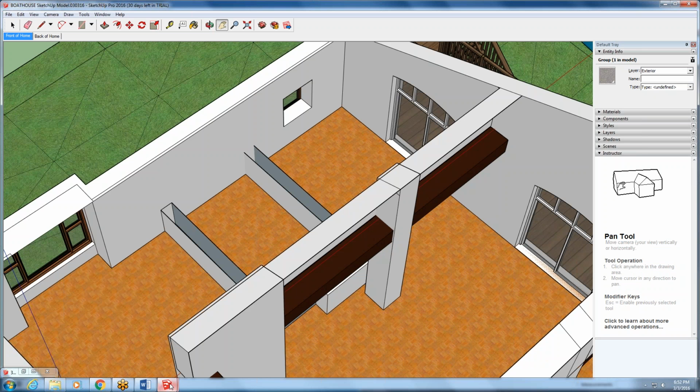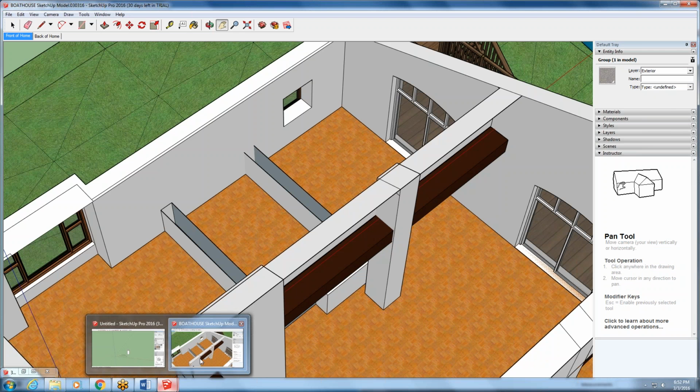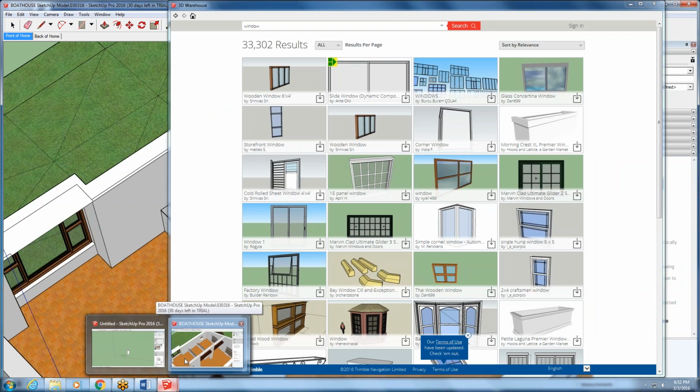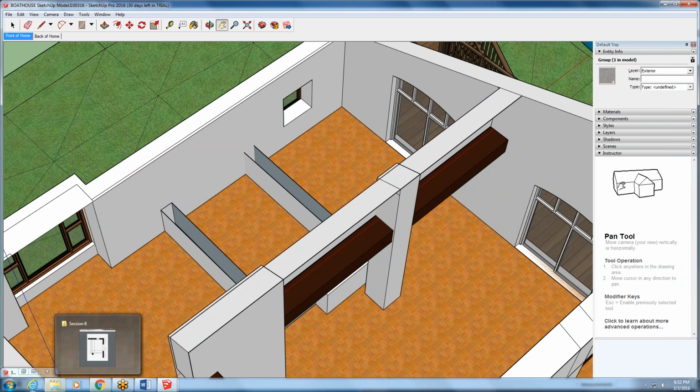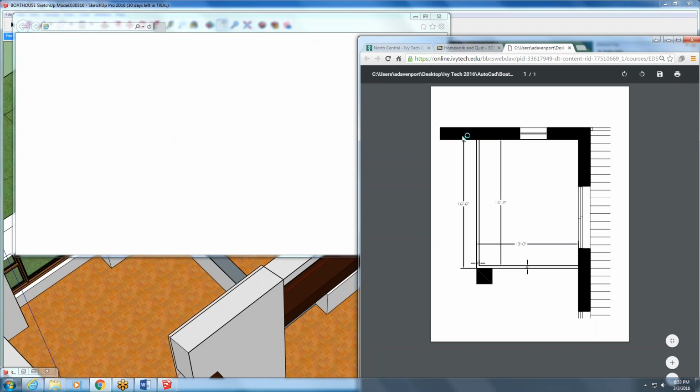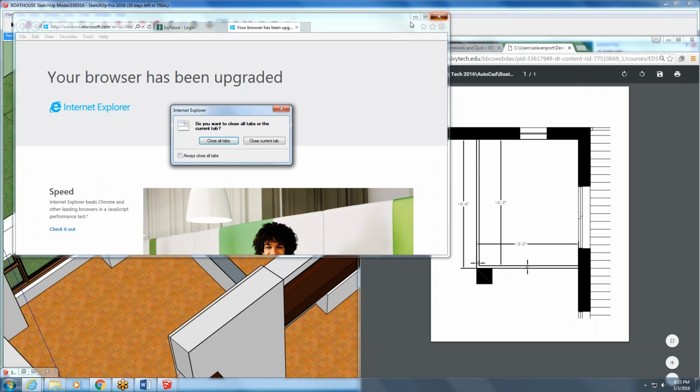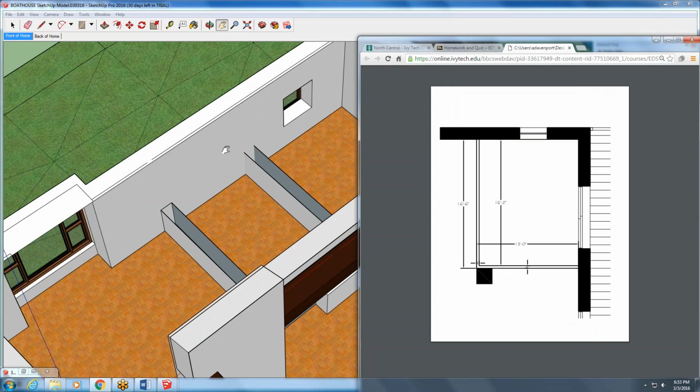So I'm asking you to draw those walls as groups according to our PDF online from that corner. So I want from 13 feet over, this one's 16'6", so it goes all the way to the column, and it's 4 inches in. So I want you to use your CAD math and your CAD brain on that front to draw the basic properties of the wall.